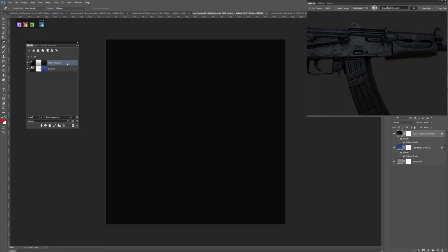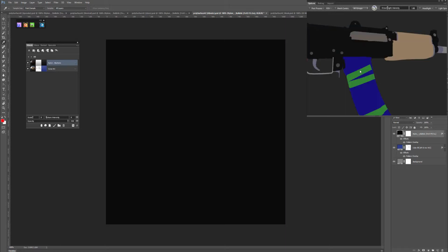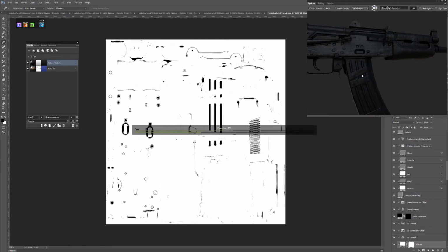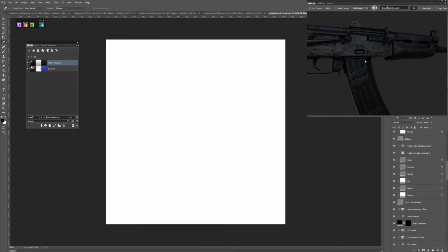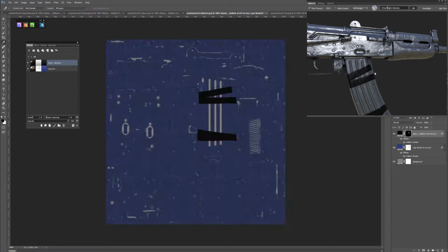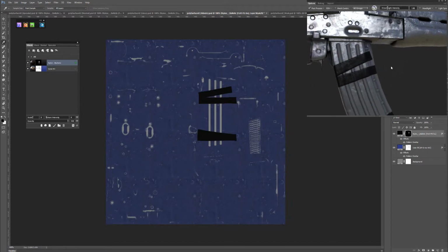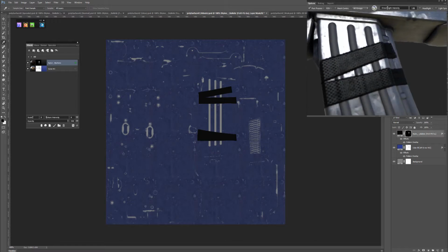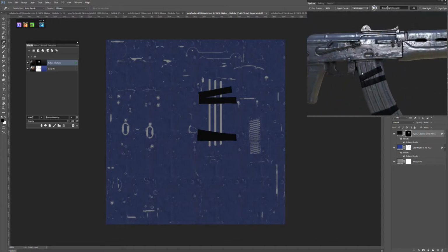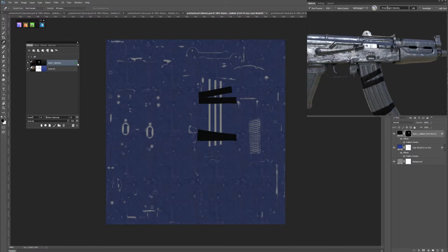I have my nylon selected here in the layers. I'm going to hold down C to bring up my color ID map, and then click on the green color. And that's going to apply a mask and just show it right here. And there we go. Now I have it just applied to this section. Very nice. I like that. And you can see here this little check box now has a color filled with the green, because that's the color in my color ID map that is being applied to. And I can of course change the scale and all of these other pieces right here.